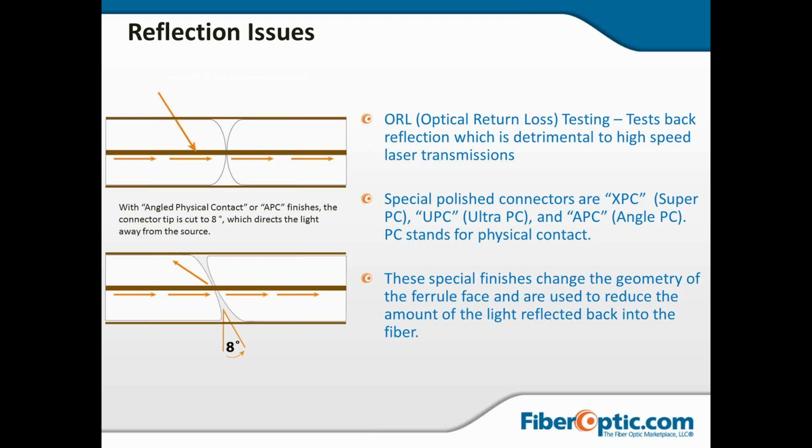Now, next month we're going to be talking about cleaning, but I'm going to mention one thing now: optical return loss is usually a function of not having the connectors clean enough. The connectors themselves are capable of very low reflections nowadays, but we have to make sure they're cleaned. I will tell this story again next month, but we were out on a job where links were failing all over the island, all over the country of Haiti after the earthquake, and they thought there was actual fiber damage from the earthquake.